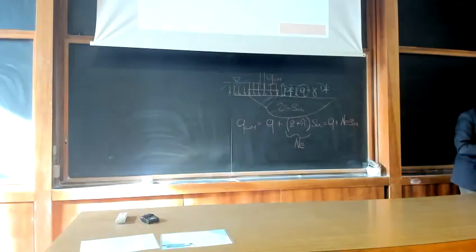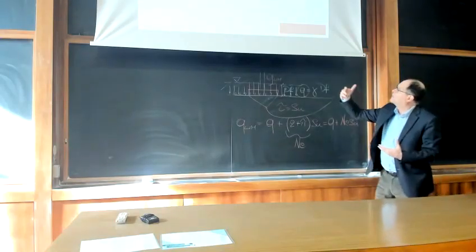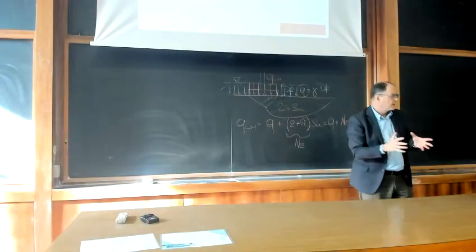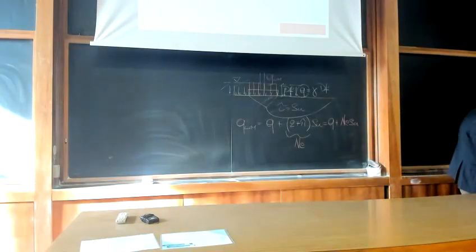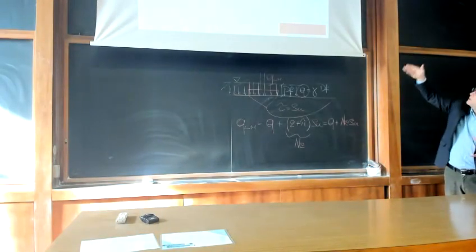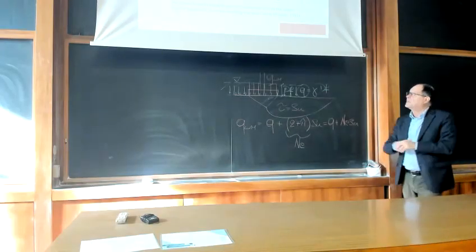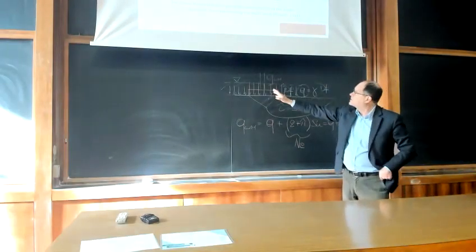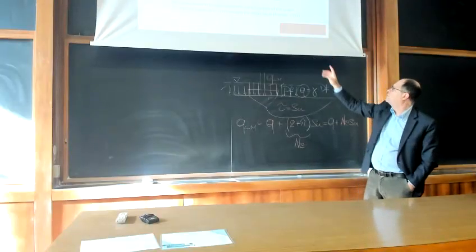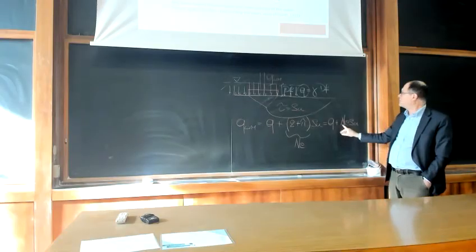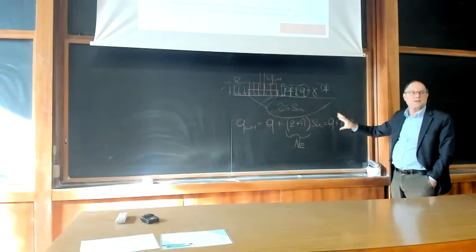Now we can think of a more precise, a better defined stress field, like this one, and of course you have to find equilibrium in all those regions. That's why analytically it is a bit longer and we are not going into the details. But the good thing is that in this case, under this assumption, we get to a lower bound which is equal to the upper bound. And this means that this is also the true solution.